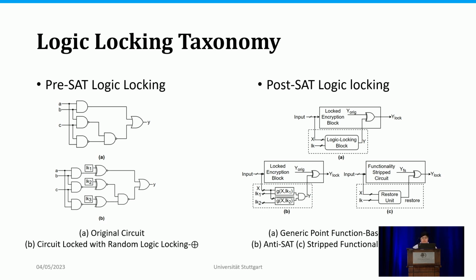On the right-hand side, you see an example of a generic point function-based logic locking scheme. These schemes introduce a single point of perturbation or error into the circuit functionality based on this point function, which again depends on whether or not the correct logic locking key is applied. Again, we consider two types of such schemes. In figure B, you can see anti-SAT logic locking, and in figure C, stripped functionality-based logic locking.